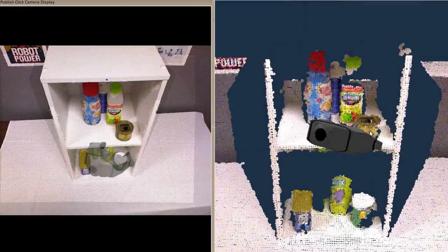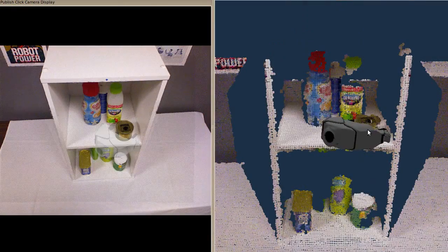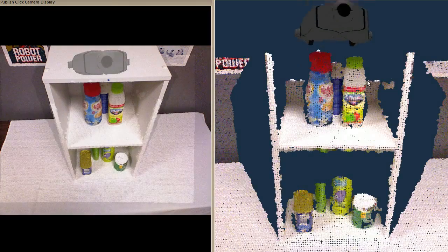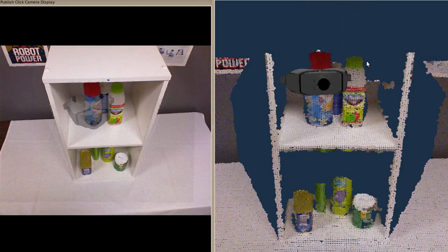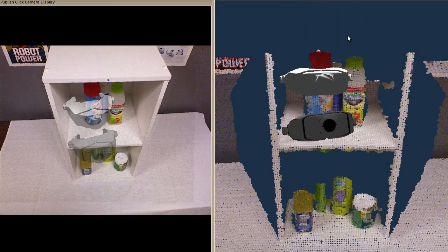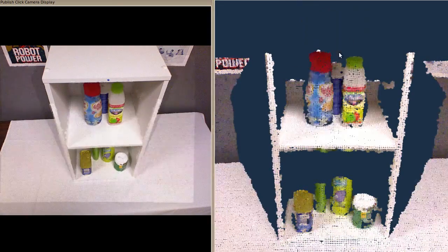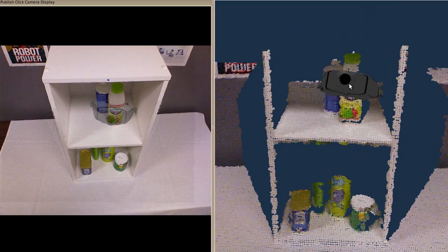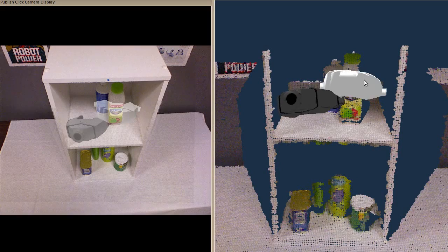Using the haptic interface, the operator can control the position and orientation of the virtual gripper model while receiving force feedback from contact with objects in the environment. Haptic feedback conveys contact information in an easily interpretable form and also provides useful depth cues that are not obvious from a single viewpoint.